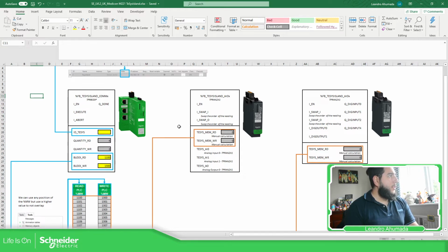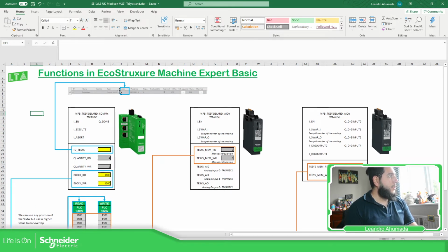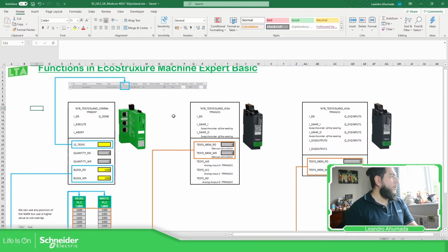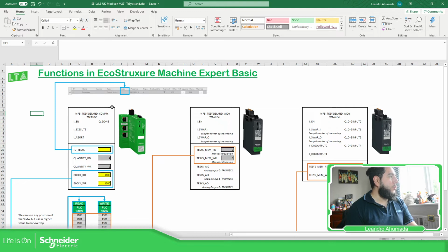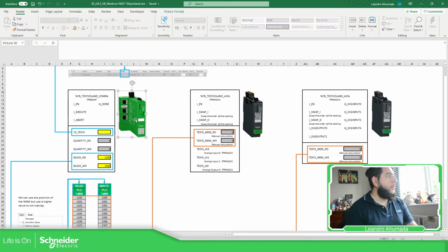So what I have done is this. In order to avoid having different equipments already configured, let's use just one equipment without using the IO scanner. I can move the information that I read using this function block that I created over here to talk with the bus coupler, which is the first module that has the Ethernet connection.